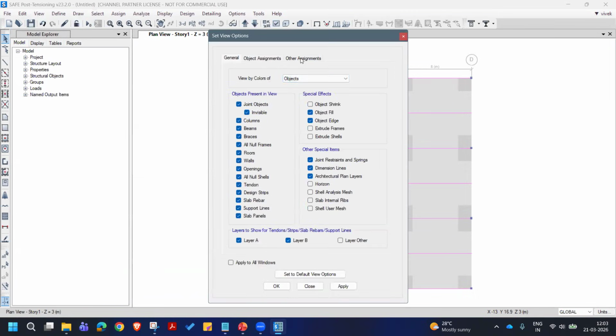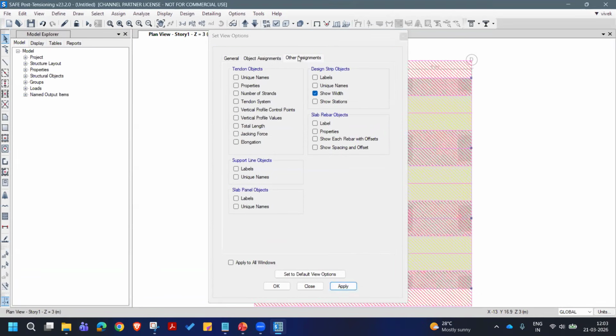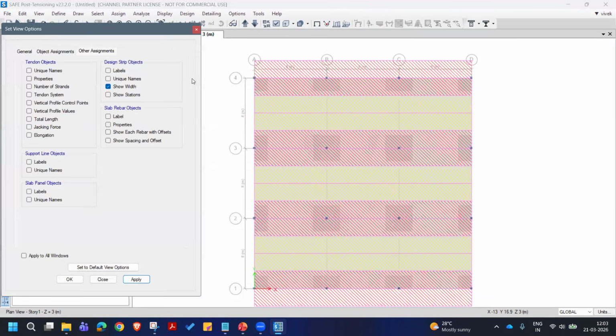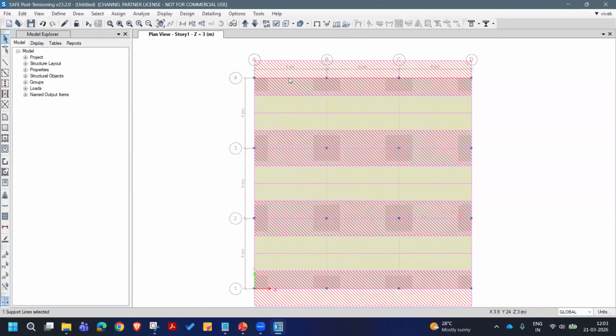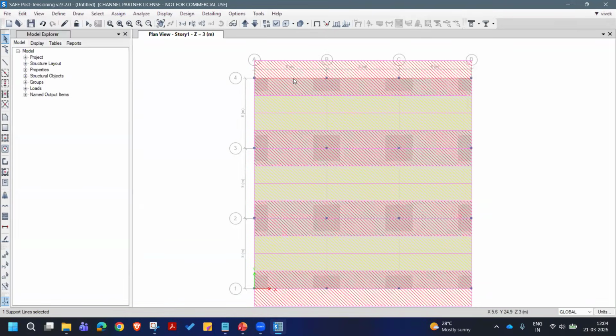Small adjustments should be made. Let us look at the width of these strips generated. Right. Those are the adjustments needed here. Here, you can see there is no physical slab here, but strip width is exceeding on the left side, so we'll have to modify this. So modify is possible by selecting strip, and under the edit, you have edit strip width, or can directly right click,